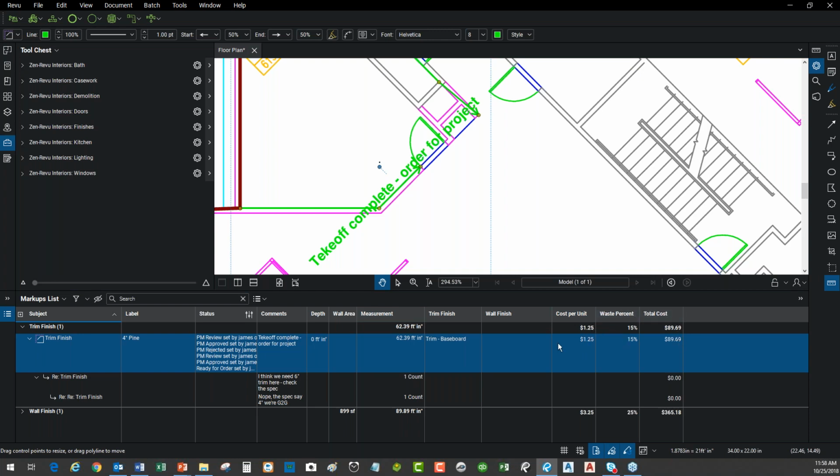I can easily go in and take a linear measurement like the trim finish or a pipe or a conduit and say, hey, I can divide that by the overall length, right? Every 12 feet. Say every 12 feet, you've got 100 feet, divide by 12. Here's how many supports or stanchions or hanger brackets or whatever I need. So look at it like this. Any calculation, Jorge, that you can do inside of Excel, you can essentially do here inside of Bluebeam as well. Okay. And I don't see any other questions coming through.